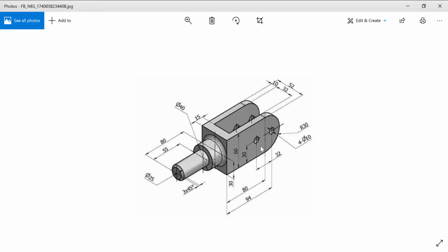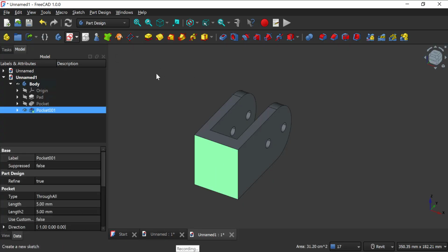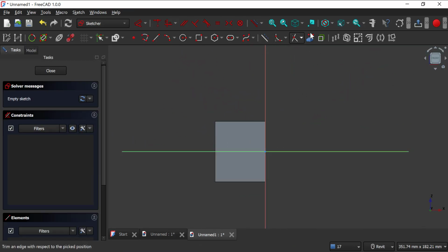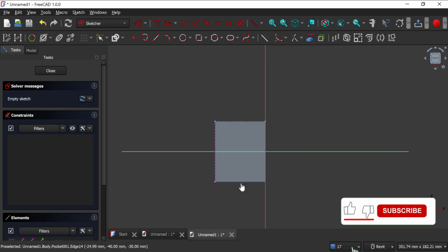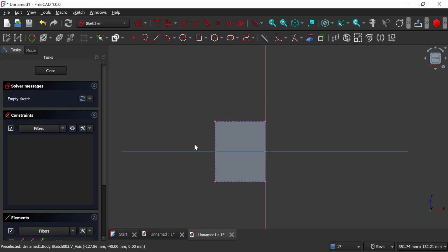What remains? The remaining part is this cylindrical part here. So let's make that one. Click this plane, and then create a sketch. Rotate your views, and then reference this geometry. It is important to make a reference of the geometry so that you can refer all your constraint from this axis, the previous part, because this is our previous part. So everything we are drawing here should be referenced from the part.